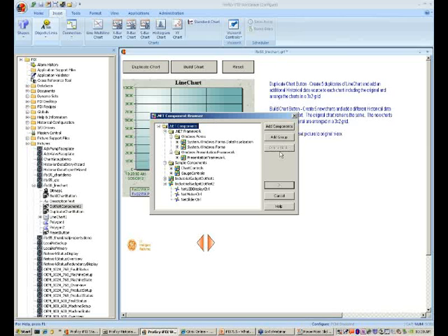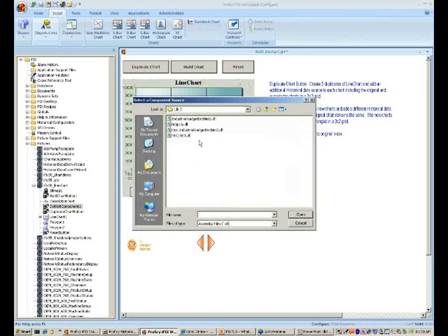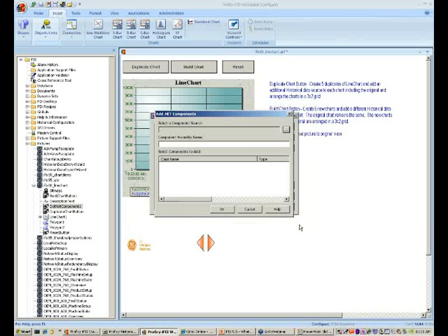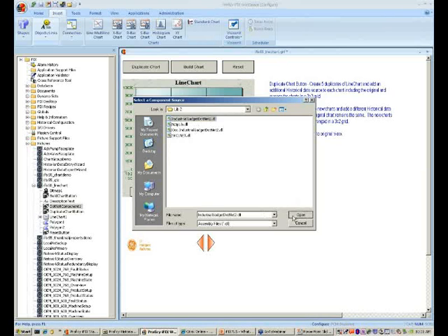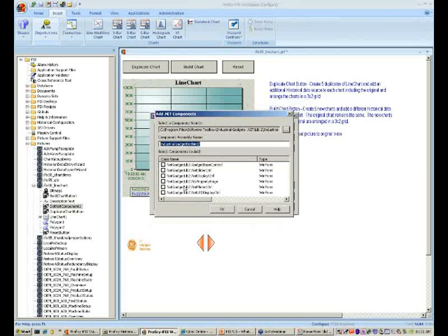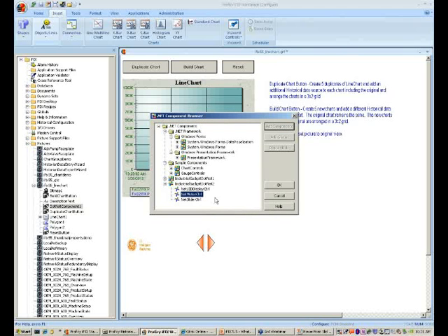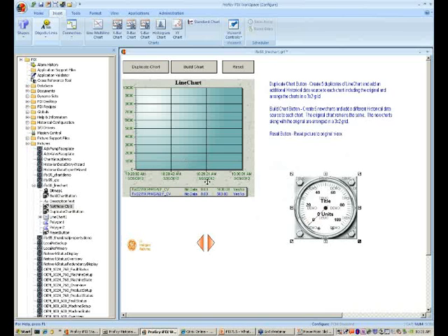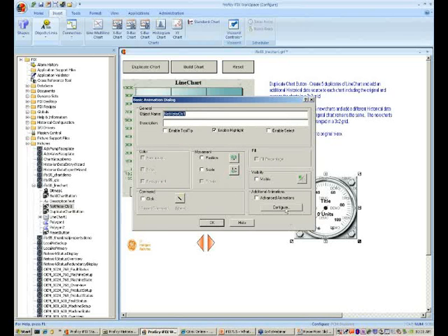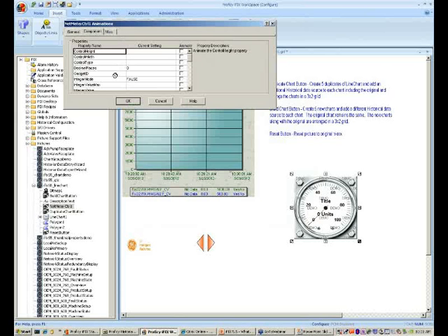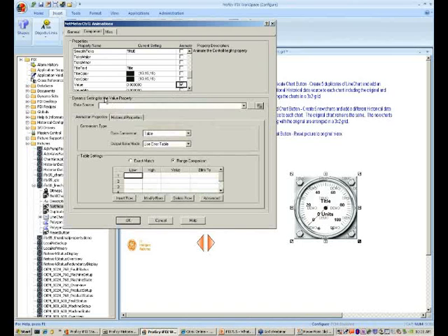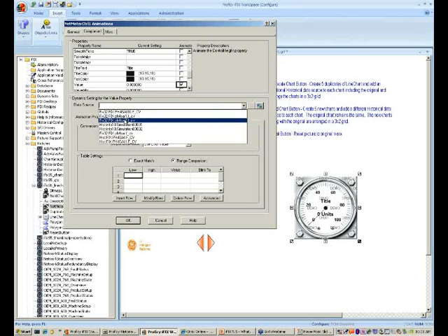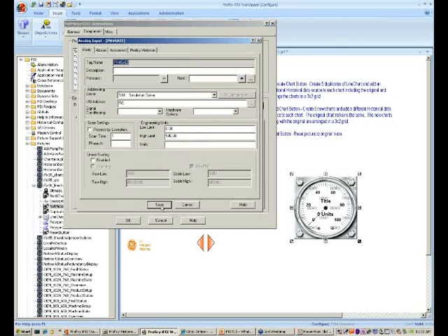And when I went to the .NET component browser and said add components, it looks for that particular DLL and then does the registration for you. If I pick the particular object I want, it finds out what all objects are part of that DLL and lets you choose which one you want to specify. So I've chosen a meter, so I'll just take a meter and drop it. It basically drops it in the same graphic that I had this chart object on. Now if I go to the animations window, there's the position and the scale, or when I go to the advanced animation, it lets me assign a value to it, and I'll just assign. And let me see if this changes it.